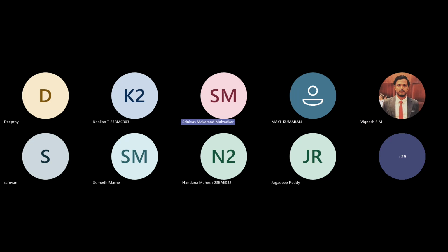And is there any connection in the CAD between the propeller and the rest of the body of the UAV? Yes, that needs to be there. The connection will be there, but surrounding the propeller, we will need an MRF zone. The connection is required. So you are saying the motor shaft should be there? Yeah, the shaft needs to be there, but we don't need the exact feature of it. Just a connection needs to be there. Then only it will be considered as one complete body.